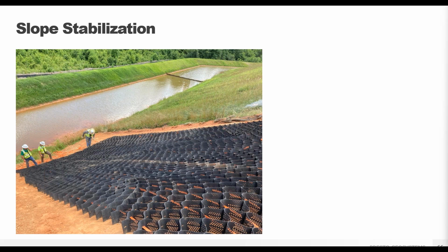Okay, back to slope stabilization and pre-assembly. The pre-assembled sections, once connected to whichever version you have of the crest anchorage, are then hung over the slope like a curtain and extended down slope.